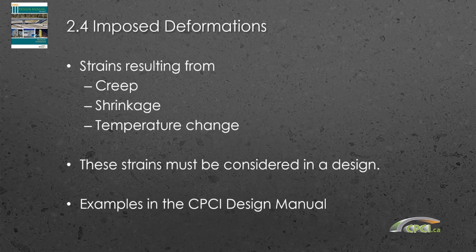A large part of Chapter 2, which as precast and pre-stressed engineering goes, cast-in-place concrete designers generally don't have to look at in too much detail, but it's a large part of designing precast buildings and other types of structures like parking garages, is really looking at the strains resulting from creep, where concrete under sustained load, whether it be the pre-stressing force that's sustained or the deflection, will soften and continue to either shorten or deflect due to creep until it becomes stable.